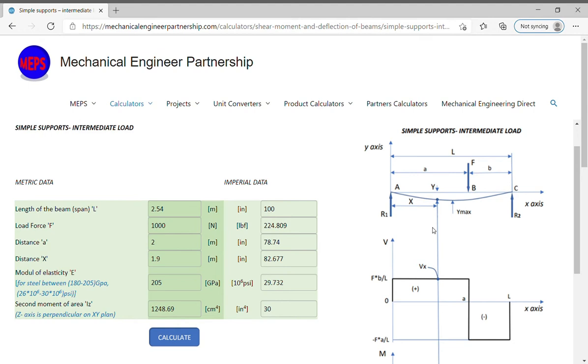The shear force is obtained by summing the forces on the isolated section. The bending moment is the sum of the moments of the forces to the left of the section taken about an axis through the isolated section. The sign conventions used for bending moment and shear forces are: clockwise for positive moments and counterclockwise for negative moments. Positive shear forces are in the same direction as the y-axis in the figure and negative shear forces for opposite orientation.